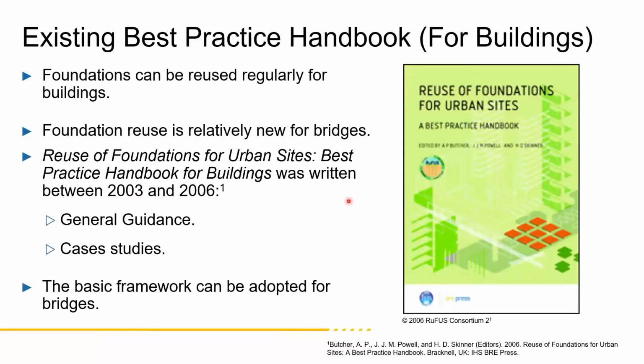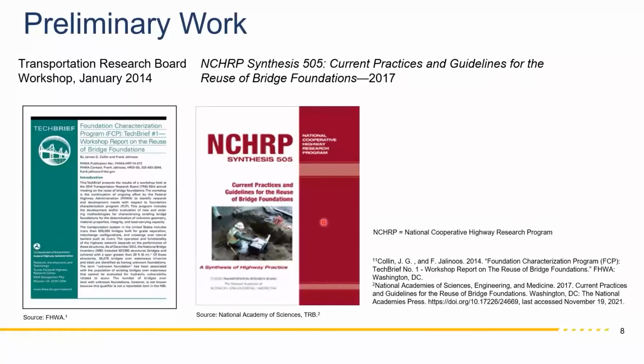It basically talked about reuse of small diameter piles that is done in the urban corridor, especially like in Chicago. And they even created a test site in BAM, which is in Germany, the counterpart to Turner-Fairbank. They created small diameter piles with pre-engineered defects, and they did a lot of NDTs with pulse-sonic and sonic echo and parallel seismic and all that sort of stuff. So they took a look at it back in 2006.